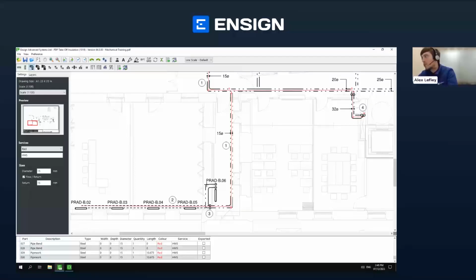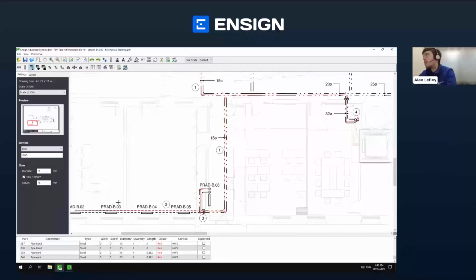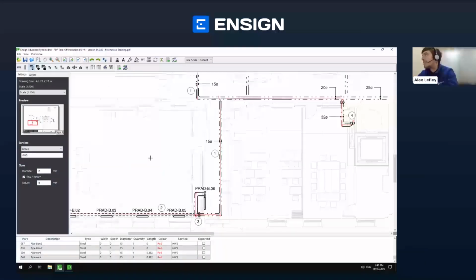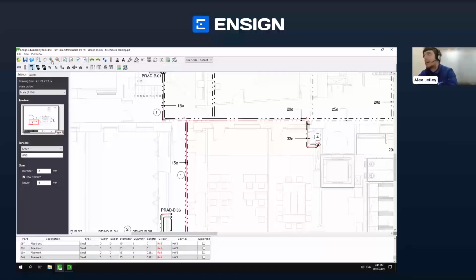So I'm just going to do this little branch here as well. Left click, left click, left click, right click. Once again, I can go around, I can allow for my various T's, valves, and everything else I would need to do. One slight recommendation for you all, if this will help you out in any way: a lot of people will do the main pipework run in one specific color because they can easily detect where bends have been added. But then when it comes around to counting up their additional fittings, they'll change color over here. So change that down to green, but still put in hot water service, just so that it's easily distinguishable when you're moving around to go, right, that is where I have my green mark. I have allowed my T there. So it's just visually easier to do these checks yourself, okay?